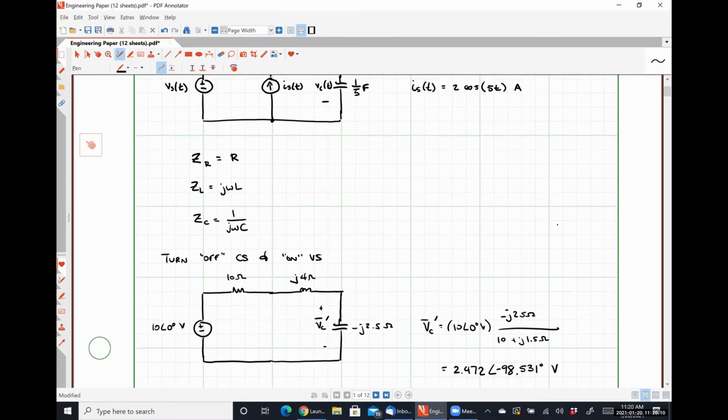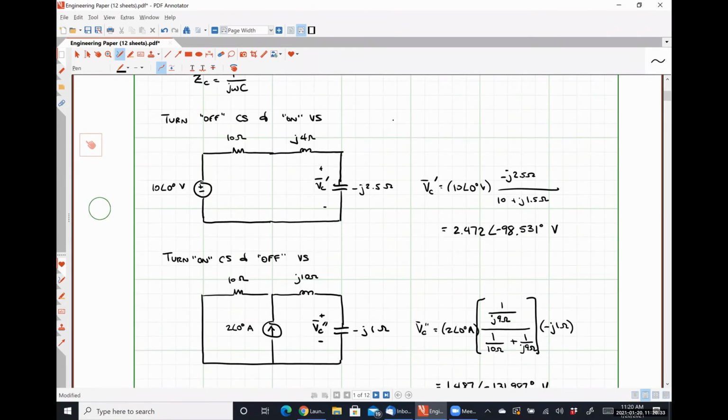So in our DC circuit analysis, we found that if we find the response with one source on and the other source off, and then we flip those conditions, we can simply add the results, right? The problem here is that we are going to do that, but we're going to add the results only in the time domain. We cannot simply add the frequency domain results together,